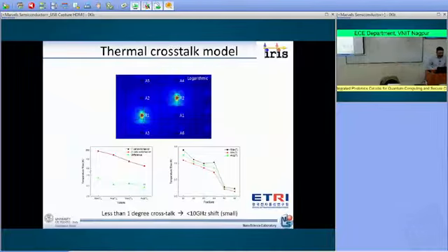In this case the heating goes up to 200 Kelvin. So now you also see the kind of temperature that you achieve: you are injecting 20 milliwatt of electrical power, and the local heating of the microring resonator is up to 200 Kelvin. So you are heating quite a lot.